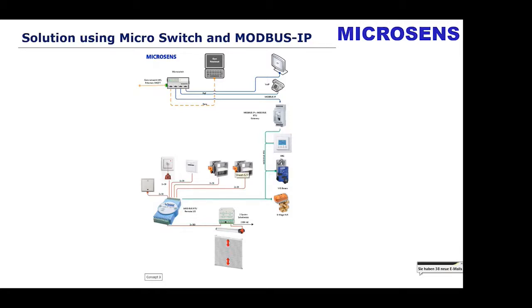So if you have a switch inside the room, which was used in the past for the room networking task, you can connect conventional IP devices over a gateway via Modbus IP, and the data from those gateways can be treated, and we can do the room automation. This was another approach, for example, over Modbus IP.